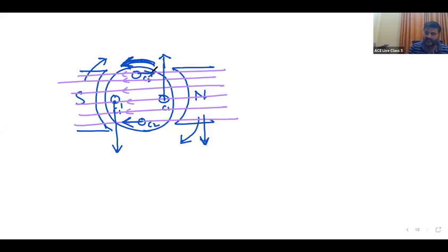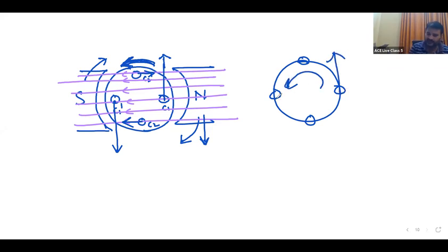Okay, tangential, na? As I told already, when conductors are moving in the counterclockwise direction, how will they move? C1 moves upwards, this one moves downwards, in this direction. Therefore, what is the EMF in C2 and C2 dash? C2, C2 dash is 0. They are not cutting any flux. This is the direct axis, this is the quadrature axis. No EMF in C2, C2 dash.